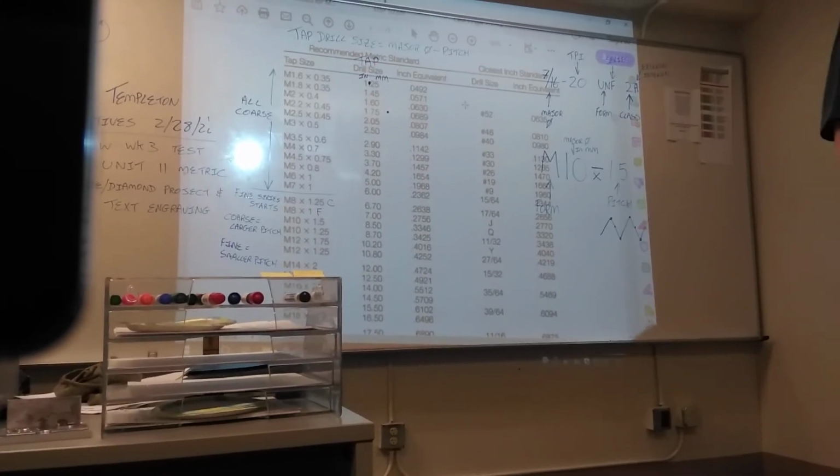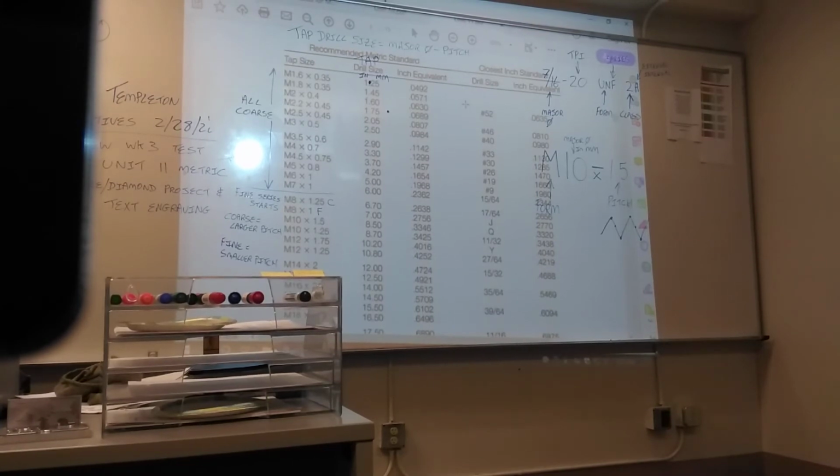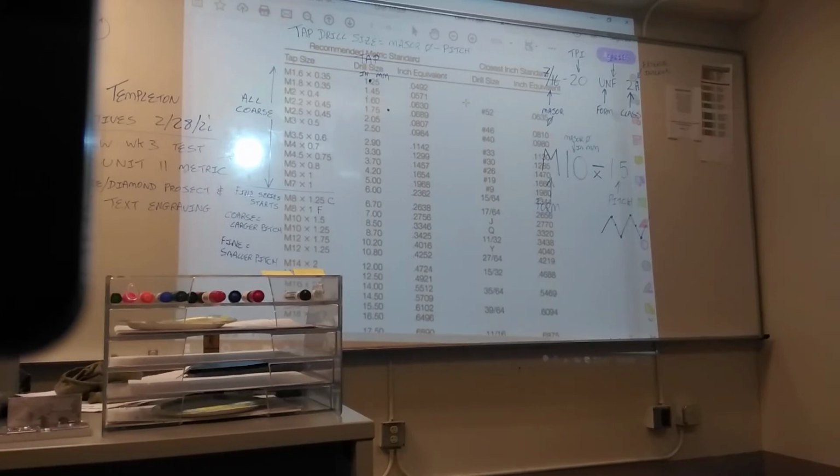Does this work for inches as well or no? It does, but when you're doing it in inches, you've got to convert that TPI into pitch. Unless you can do 1 divided by 28 in your head, it takes a little bit more work. So you're subtracting the pitch from the major diameter. That's all I'm doing. Very simple. Don't need to go walk across the shop and find the tap drill chart, or go to your toolbox to figure out what size drill you need.